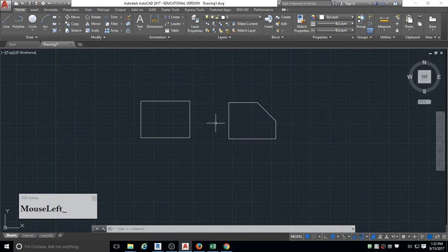Last thing, I said that polar tracking could also be used to position. So I'm going to draw a circle that is 45 degrees. Oh, I can only get horizontal and vertical. Now this is the trick. With snap tracking, for polar tracking, it defaults only to horizontal and vertical.